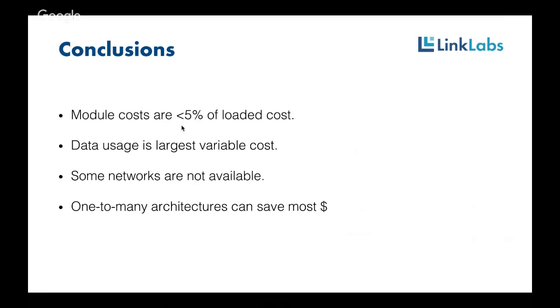Glenn, are there any questions that have come up? Isn't the battery cost of cellular solutions way higher than LPWAN? I would say, the power budget of LTE-M versus a technology like Sigfox or LoRaWAN is higher. It's about 30% higher bit per bit if you use PSM and eDRX well. But the difference is when the LTE-M module is transmitting and joining the network, it needs to draw more current than you need with an LPWAN technology. So that forces you into bigger or more expensive batteries.